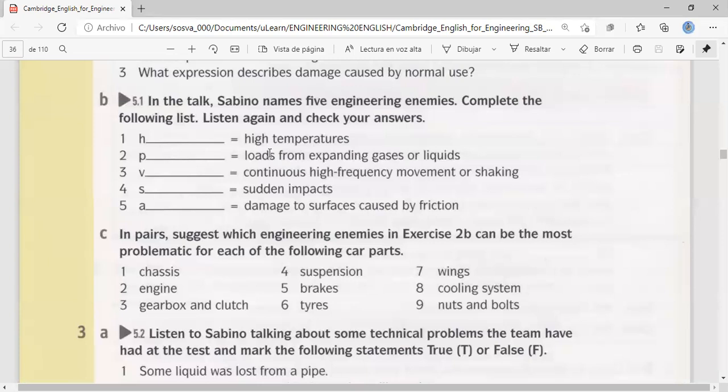We can get fracture, well, impacts. What else? Vibrations. Exactly. The vibration affects the nuts and bolts a lot. Because if it vibrates a lot, then the nuts and bolts might fracture or disassemble or something like that, in some drastic cases.